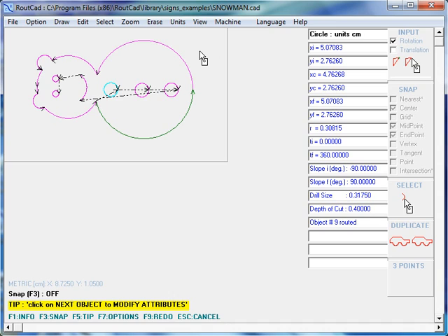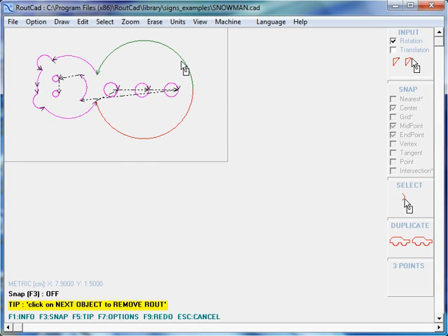To fix that, we're simply going to erase the route. We're not going to erase the part. We're only going to erase the routing information. We go to the menu Erase, and click on Route, and we can either erase by selecting a segment one at a time. So see, we erase this one, so this becomes first, and we erase that one, that becomes first. We erase that one, that becomes first. If we have many objects to erase the route, we could just do a window selection by clicking over here and selecting all the objects we want to erase the route. So now there's no more routing information. It's only construction element. So we'll continue.